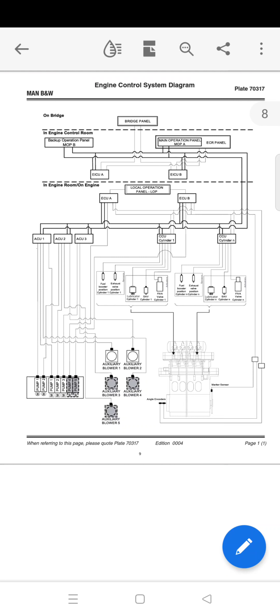Now, the main operating panel is the human machine interface through which the engine control system and thus the main engine is operated. The human machine interface is nothing but a marine approved certified PC. This PC may be one of two types, an integrated unit with touch screen or a standard PC. An actual installation comprises two MOPs. Typically, type 1 is used for MOP A and type 2 for MOP B, where both are placed in the engine control room. Each MOP may be any of the two types.